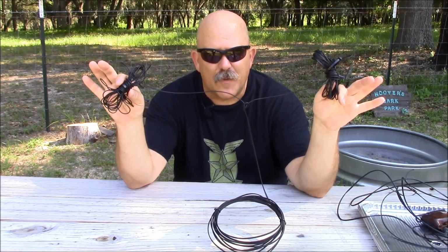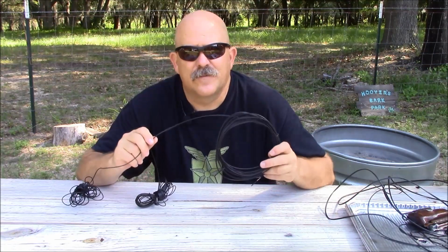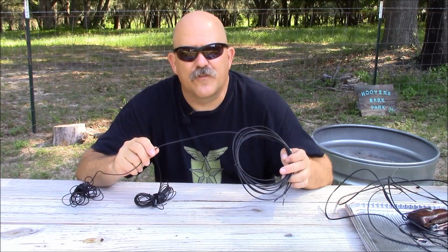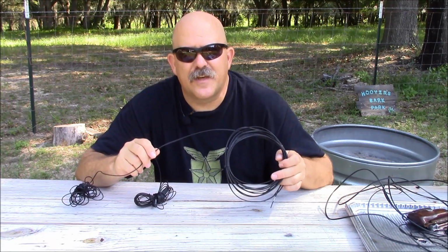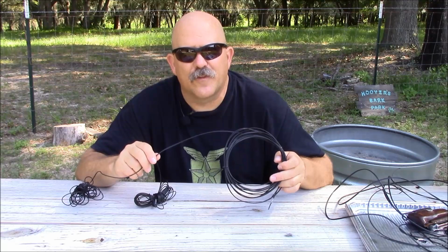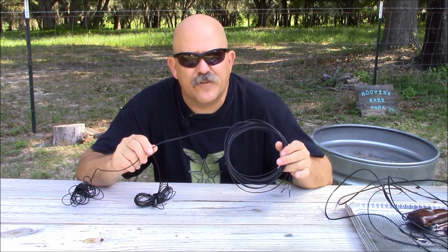3 years ago I did a video about making a simple HF wire dipole out of WD-1A military phone wire, and it's really easy. All you do is take a section of WD-1A wire, measure down a quarter wavelength on that wire of the frequency of interest, split that out, and with your 2 conductors right here, now you have your dipole elements. Tie a simple overhand knot where your feed point's going to be. To determine the length of your feed line, it's really simple. It's any even integer multiple of a quarter wavelength. Then multiply that times 0.6 and so on and so forth.